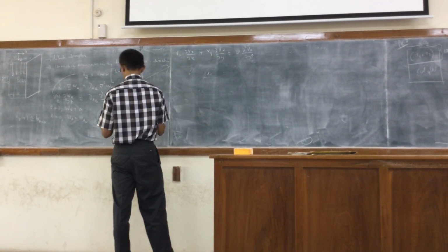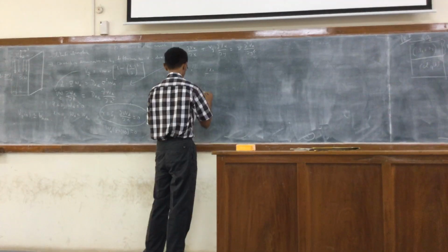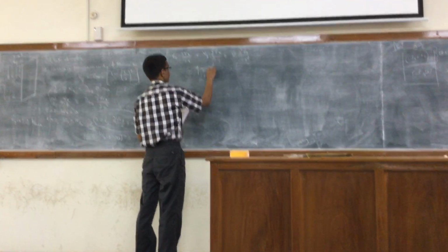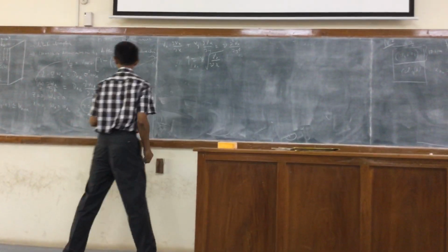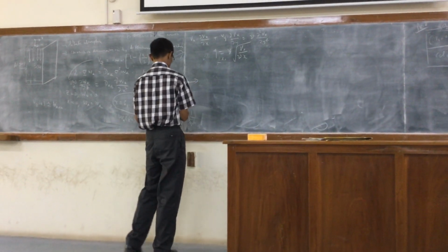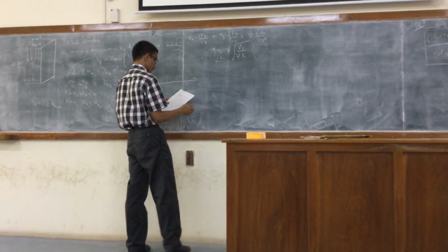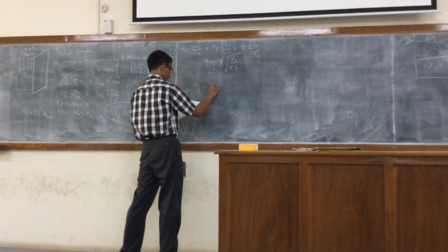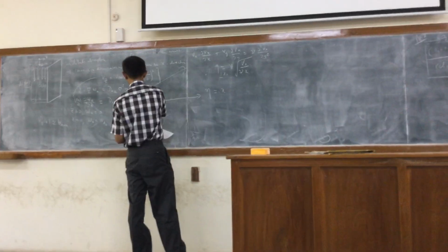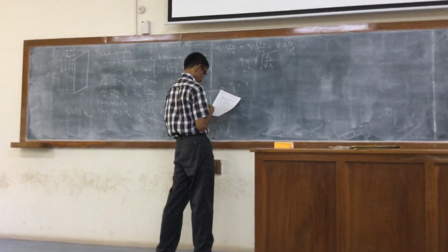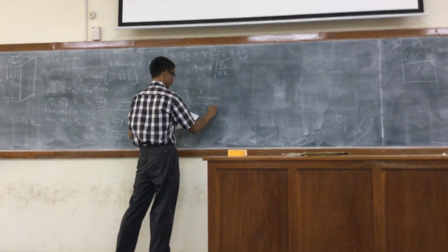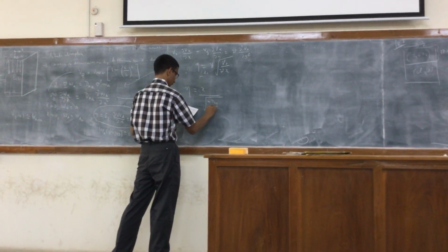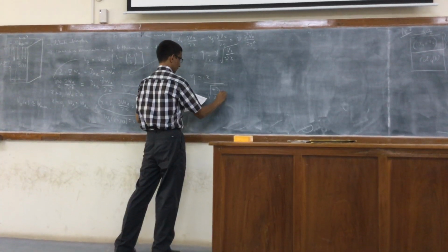So in there, you can see that we introduced an eta similarity transformation, because y times the square root of rho naught by mu x. And here, the analogous transformation is eta in terms of x. You see the second order term here is x by the square root of 4 D_AB times V max times z.